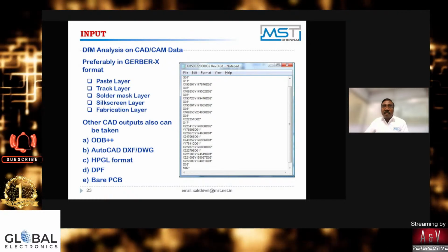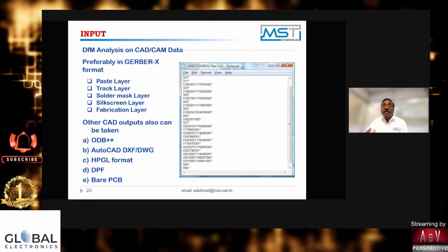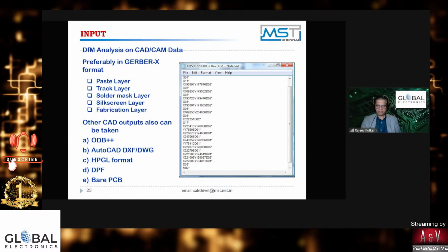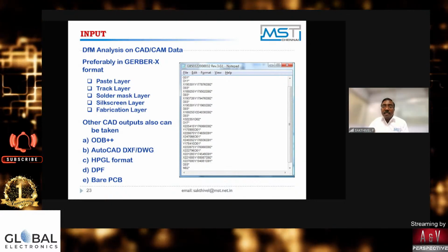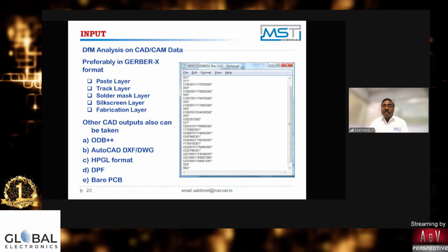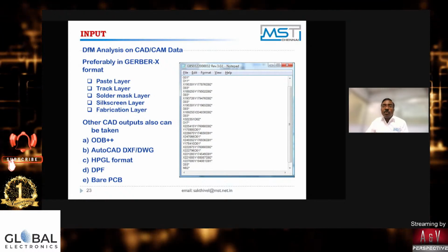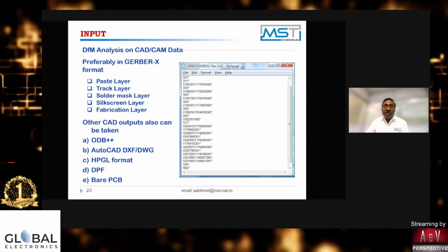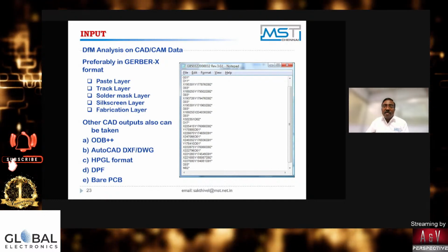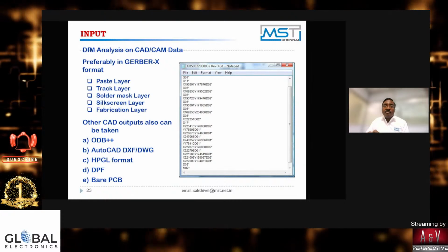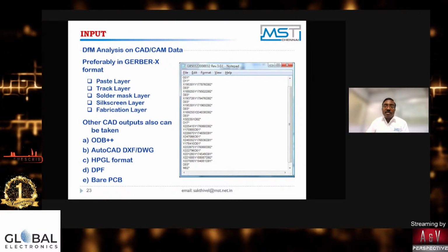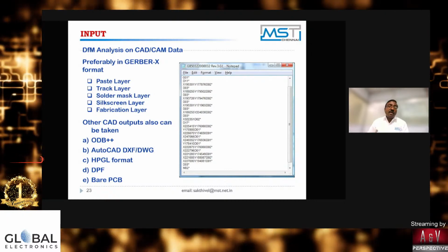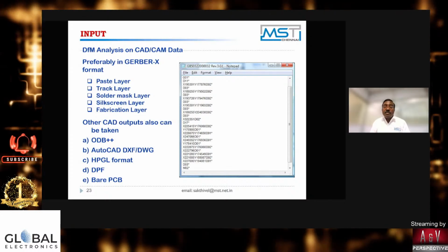There are many occasions. Very recently, what I'm facing is the PCB getting shrunk. There is also a scaling effect in PCBs, which customers don't understand. They think that a PCB, a printed circuit board from the supplier, is generating a 1:1 output, but not so. There is a scaling variation, which is within the limit as per the IPC standard or customer standards, but still that affects your stencils. So there are many process issues going on. So they should understand this design activity or PCB activity.